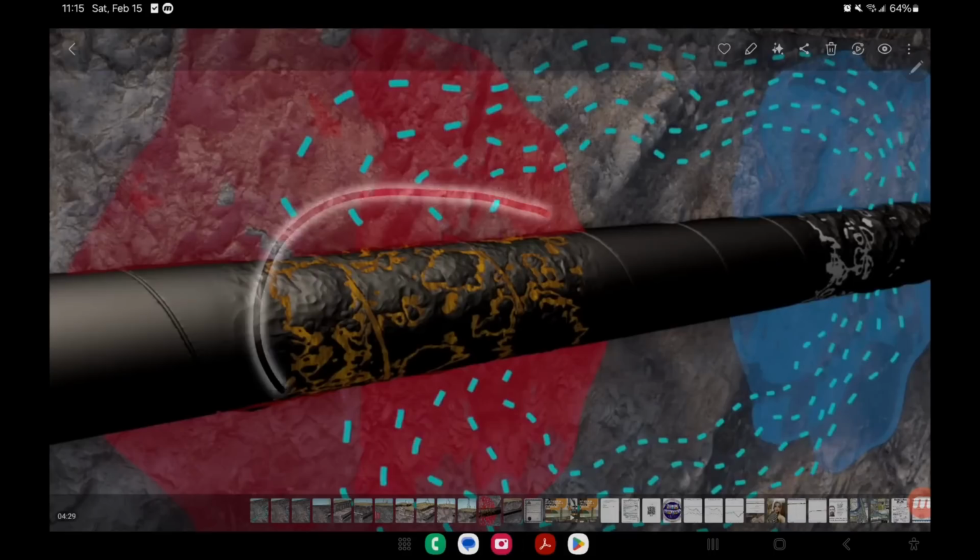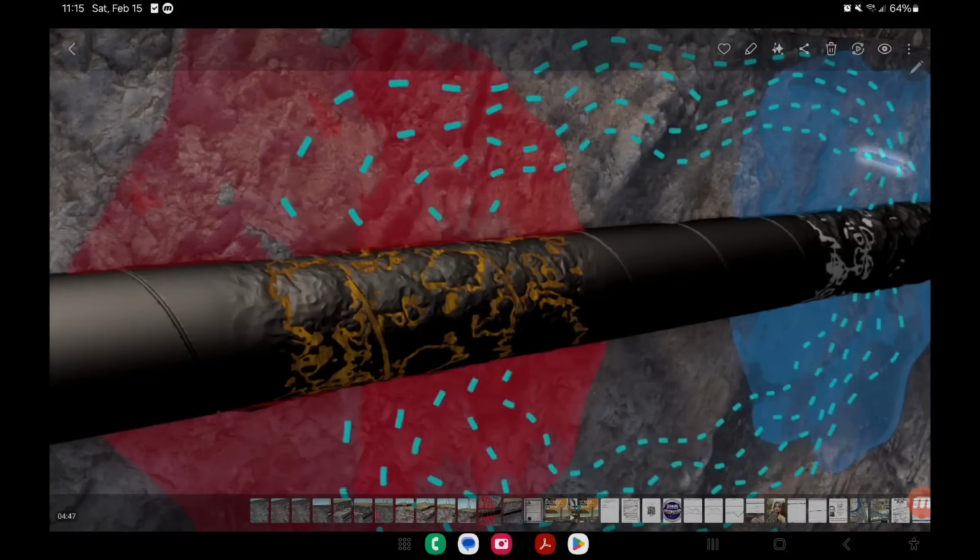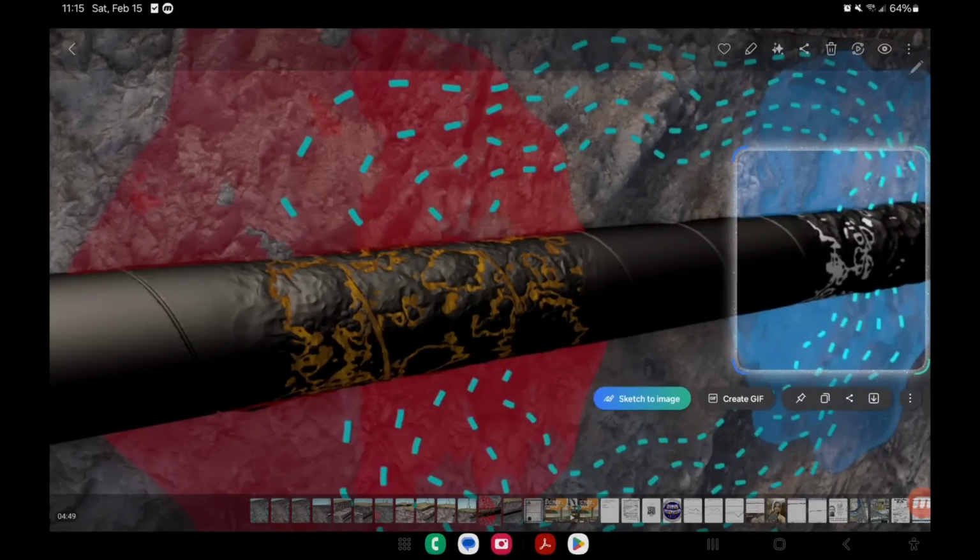We would have an anodic zone where the pipe is oxidizing, losing metal thickness due to oxidation, and will eventually fail, collapse into massive leaks or product spills. And there is a zone that will receive the protection current where this occurs in these scenarios.